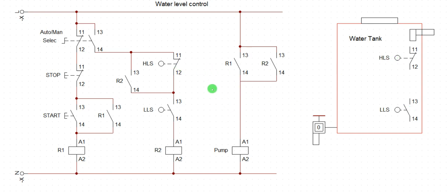Okay, but for a more elementary method, this cable is supposed to go to the tank and terminate here, then come out from here back to 12. I repeat, terminal 11 is supposed to go to the tank and terminate here, then come back from 12 and terminate here. Okay, so that is the connection. Then this one again, terminal 13 is supposed to go to 13 here and come back from 14 and come back here. So here is supposed to be blank.